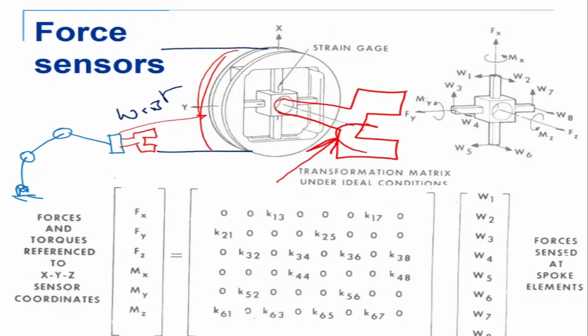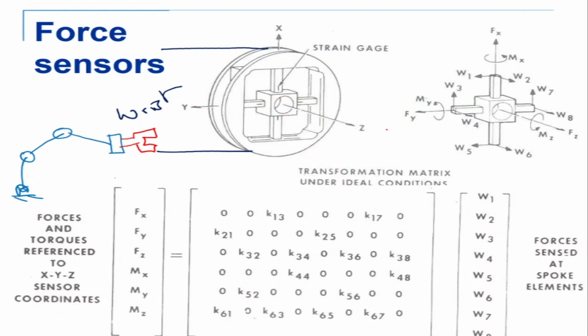So the forces and moments should be acting on the end effector, right? And which is felt by the robot. So the forces and moments are acting on the gripper or the end effector, and they are being transmitted onto the wrist of the robot, as is shown here. So this is my FT sensor. Now on the force torque sensor, you can see that there are 4 beams, and on the 4 beams, we have strain gauges, one here, here, and there. My axis notations are given like this. This is my x-axis, this is my y-axis, and that's my z-axis, which is coming outward. Now, in each end of the cantilever beams, remember that this is a cantilever beam.